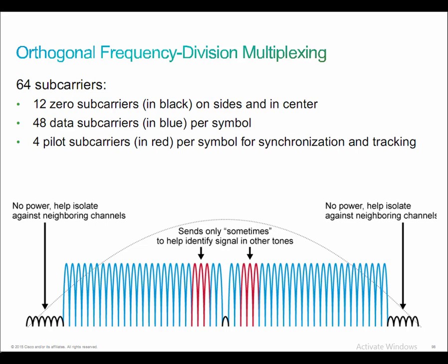When we're dealing with coded orthogonal frequency division multiplexing, we have forward error correction and time frequency interleaving that get applied to the signal that's being transmitted. This is done to overcome errors in mobile communication channels primarily affected by multipath propagation. OFDM was actually developed in the mid-'80s, I believe it was. It came out as a modulation technique, but it wasn't really adopted to wireless until much, much later.